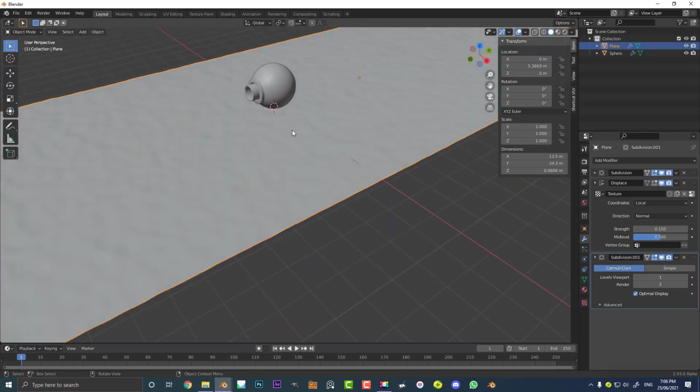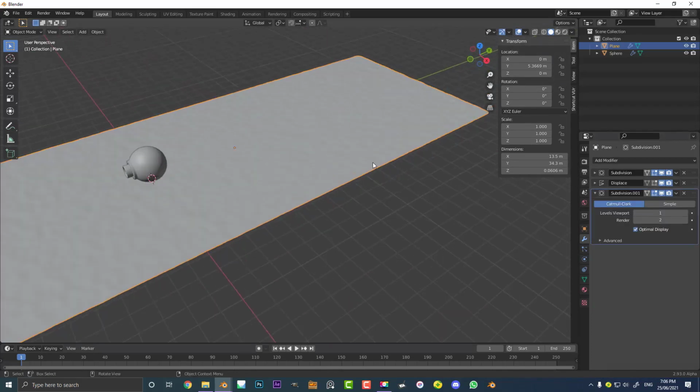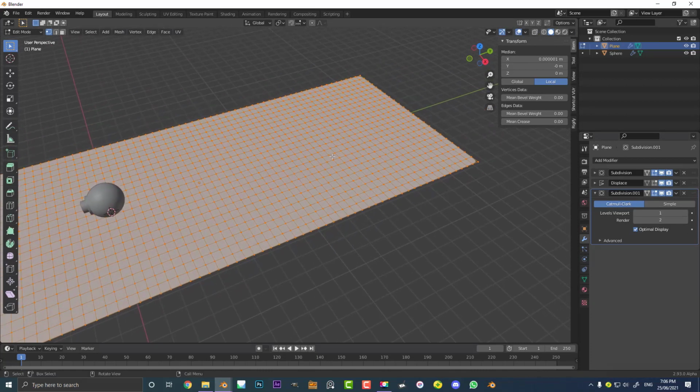So that's pretty cool. It's not perfectly flat. You can always adjust it later if you feel it's needed, but let's just quickly tab in. And just for a bit of extra displacement, we're going to cheat and come up here to the proportional editing, make it active. And we're going to come to the drop down and set random.